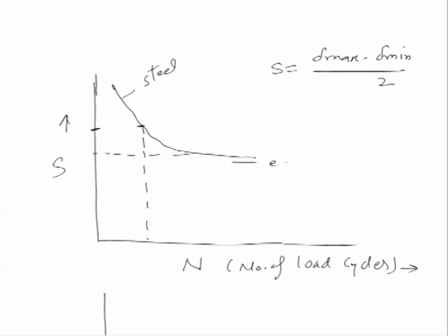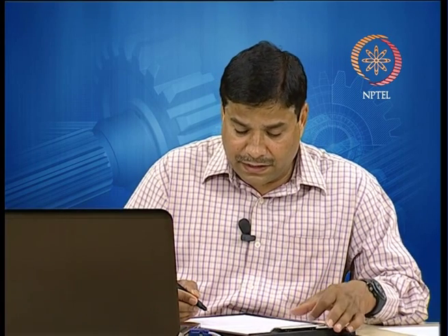So, this limit is called the endurance limit, the limit of the stress amplitude below which the component can perform for an infinite number of cycles. So, the component will not fail under the fatigue conditions.